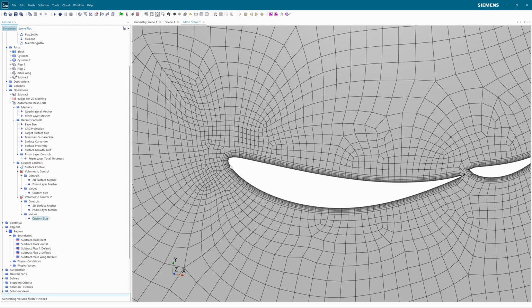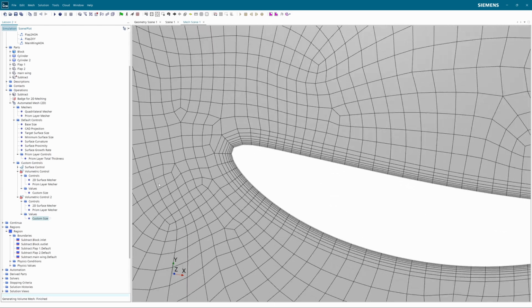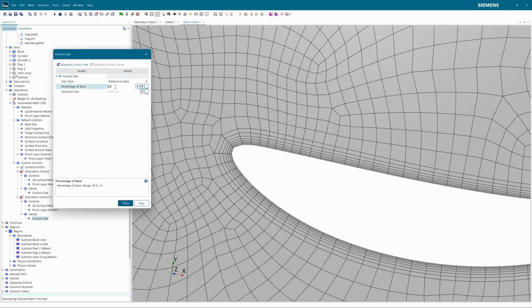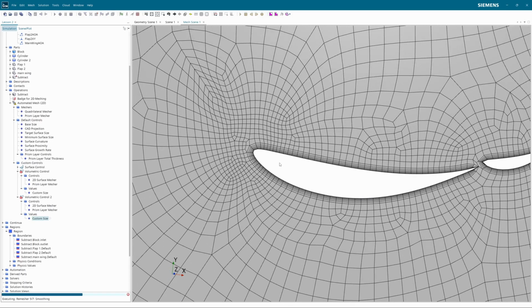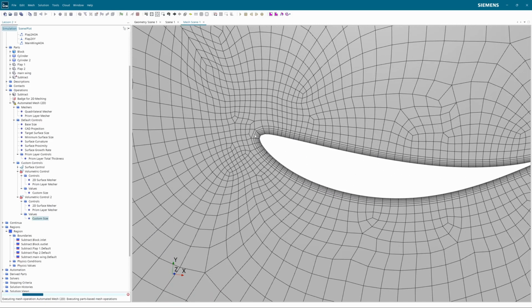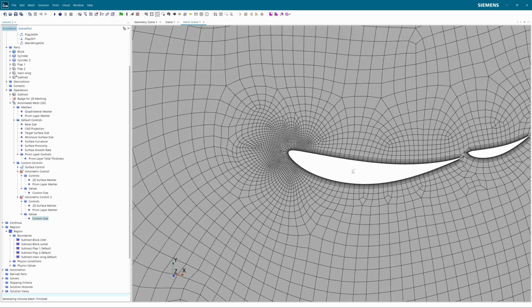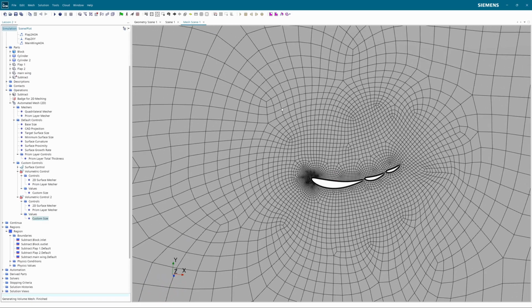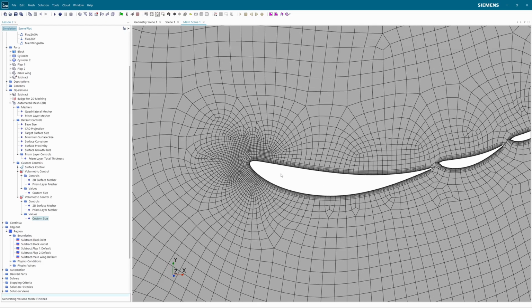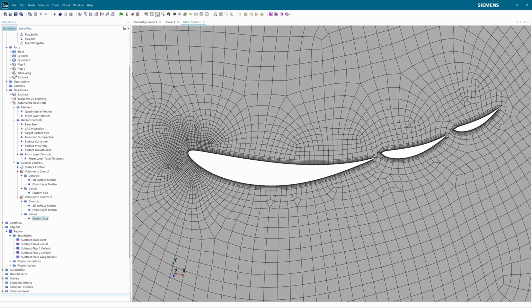All right, so that at least adds more detail. It might still not be enough, so you can just go to 2.5, and in this way you can specifically increase detail at specific locations, such as the leading edge of your wings, without actually increasing it anywhere else where you might not need it. So right now, after this, I will show you how to make sure that this happens at these other wings in a way where they also move. I will show you how to parameterize that correctly.